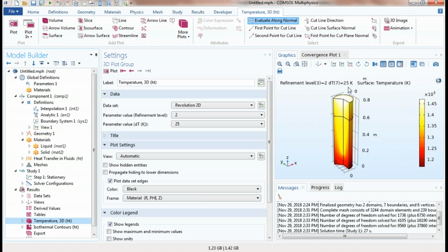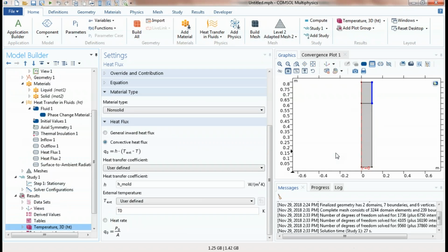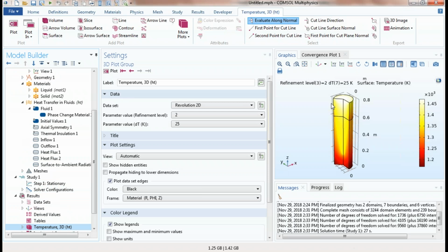So we're looking at the problem in cylindrical coordinates here. What I'm applying when I'm applying the heat flux here on the boundary is the heat flux around this entire outside surface. So you wouldn't typically specify the heat flux at the center of the geometry, which is what you would do if you were applying it on the left-hand side of that 2D model. Great, thank you.